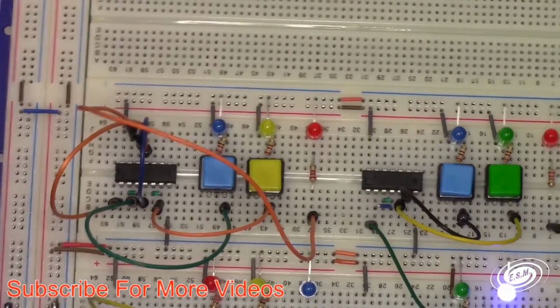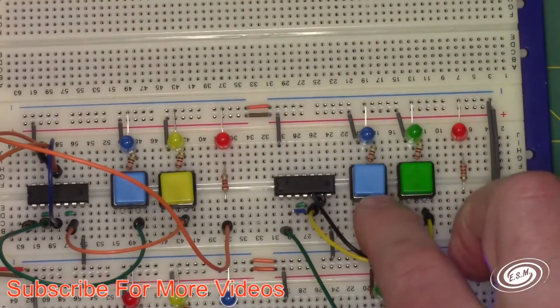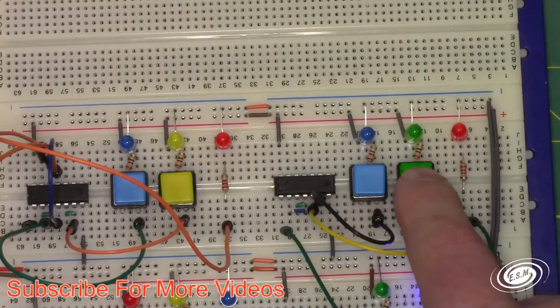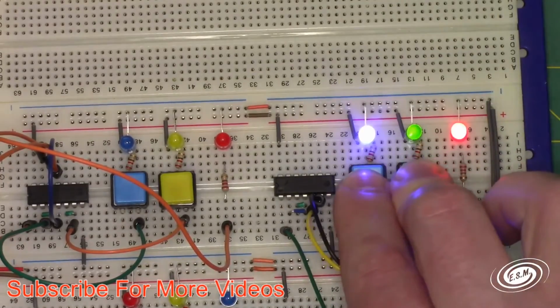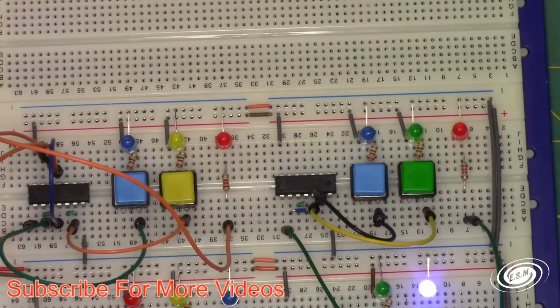If you can see that, let me put that back on there. So 0, 0, so off, and then 1, 2, 3 are all ones, and that's the truth table for an OR gate. So as you can see, with the NOR gate, I was able to make the NOR function and also the 3 basic gates that make up most logic, actually all logic, and they're just combined to make more complex logic.